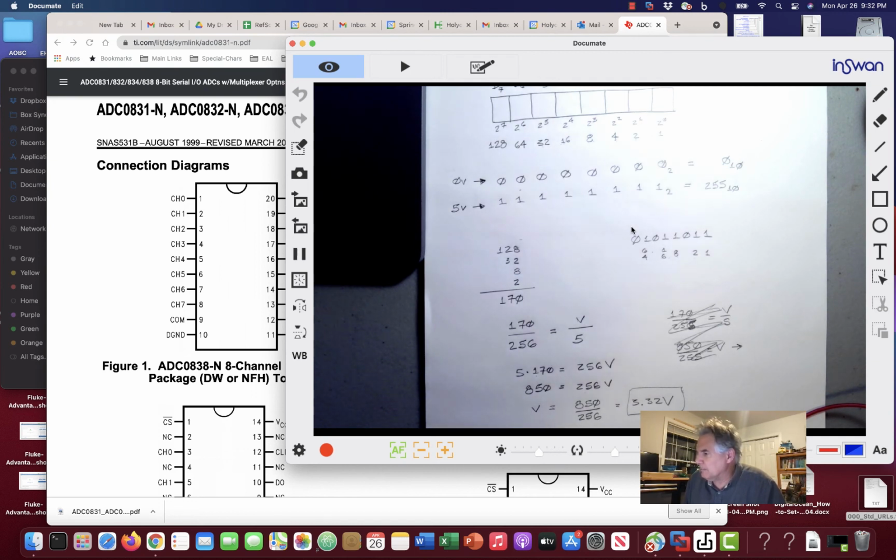And by going through all that, you see, in this case, bits were communicated serially, one after another, using only 3 wires instead of, with 8-bit, you would need to read at least 8 wires, and you'd probably need a 9th wire to say data is valid kind of thing.